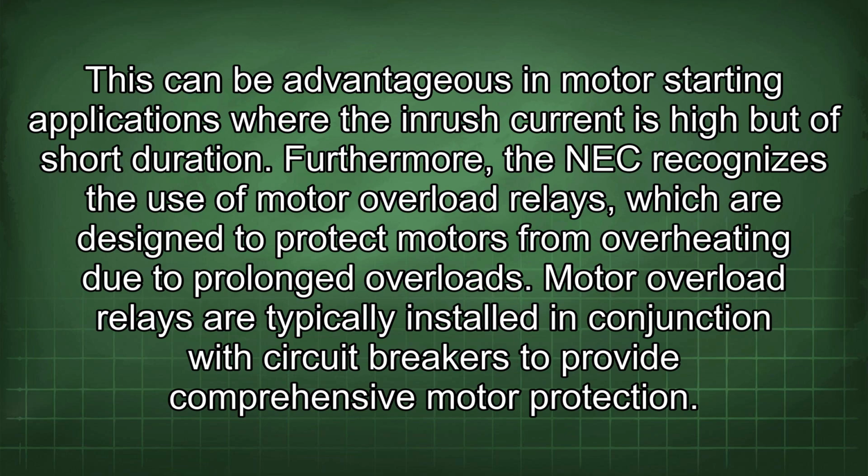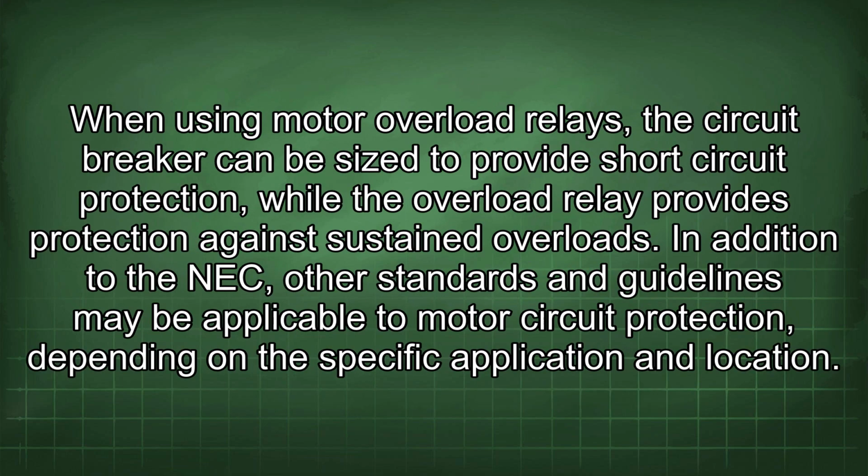Furthermore, the NEC recognizes the use of motor overload relays, which are designed to protect motors from overheating due to prolonged overloads. Motor overload relays are typically installed in conjunction with circuit breakers to provide comprehensive motor protection. When using motor overload relays, the circuit breaker can be sized to provide short circuit protection, while the overload relay provides protection against sustained overloads.